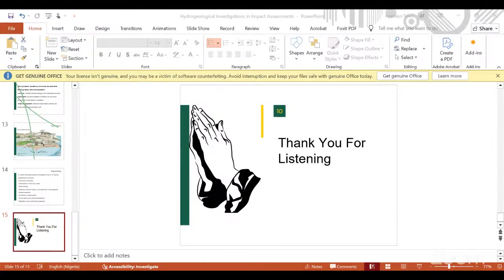Thank you. So secondly, you said casing. Yes, there is no borehole that you will not case. If you don't case that borehole, it's going to collapse, and then you would have to start another process of rebuilding or reconstructing a borehole. So casing is needed so that the surrounding walls of the borehole will stay.